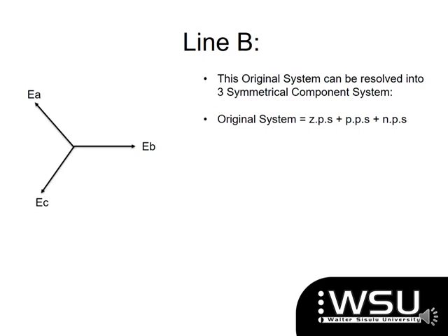So we twisted the knowledge even more for some of you. And instead of referring to line A, we referred to line B, and on some we even referred to line C, because the bottom line is that you've got a three-phase system, and really any of those three phases can be transformed into a zero, positive and negative phase sequence. So as much as we've been used to doing it in A phase, in reality B phase can be done and C phase can be done. So in the test we did this, and most of you were not able to do it.